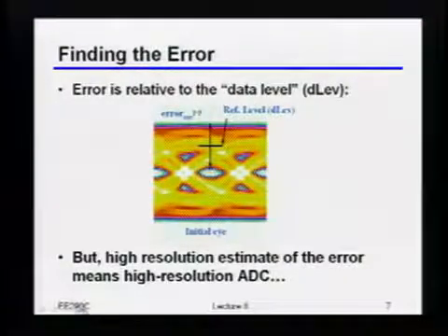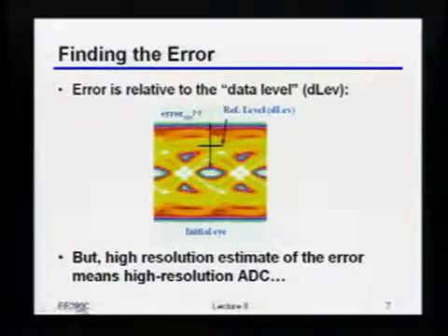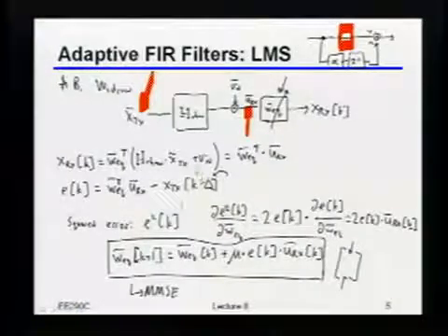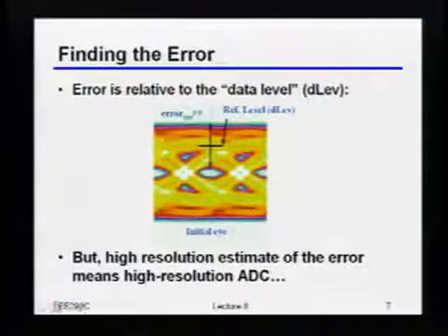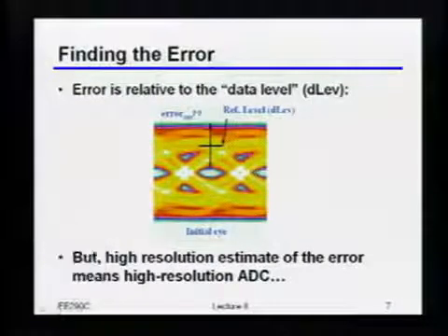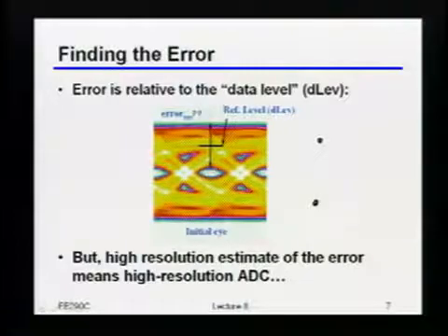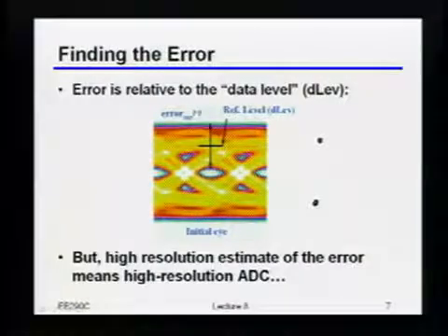First of all, the reference level you'll generally use is this. Back here, when I said that I was subtracting out the transmitted analog value, what I really mean is that, and somebody actually pointed this out, if I had a perfectly good channel, then there should be only two values coming into my receiver, quote-unquote +1 and quote-unquote -1, which of course corresponds with some analog voltage.